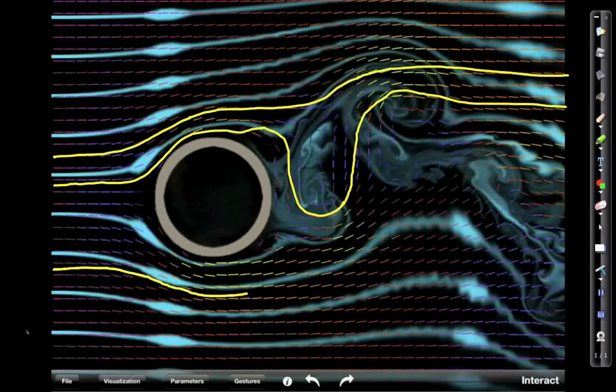So we can see that those smoke lines that are in here and those with those blobs on it were not at all streamlines, not in any general sense anyway. Here you can see I'm crossing over these smoke lines back here, and they're not coinciding. Up here, upstream of the cylinder, however, they do tend to follow these smoke lines. And as we go along here, I think those are kind of the same, and then they sort of deviate here. So somewhere around this point forward, at this instant, they seem reasonably close, but downstream, all bets are off. So those smoke lines are definitely not streamlines.